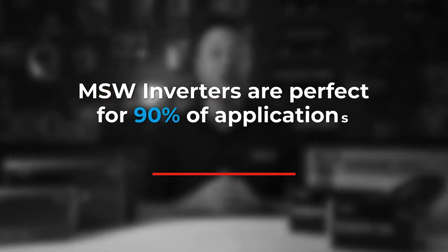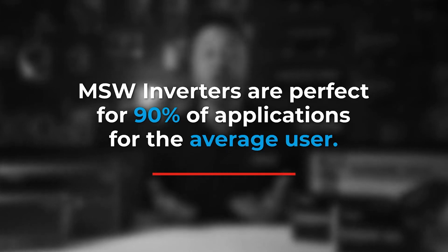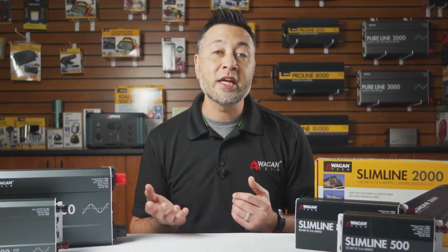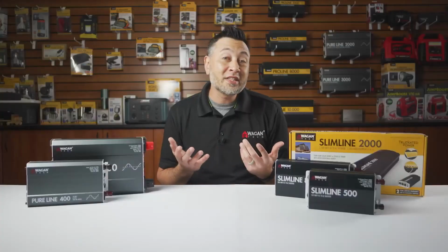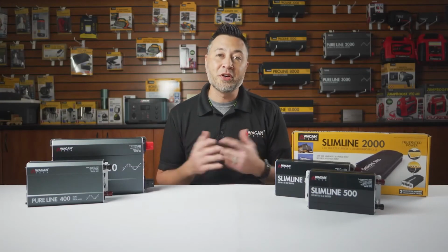MSW inverters are perfect for 90% of applications for the average user. You must realize their limitations and use them accordingly. Want to err on the side of caution? Buy a pure sine wave inverter, and you cannot go wrong.